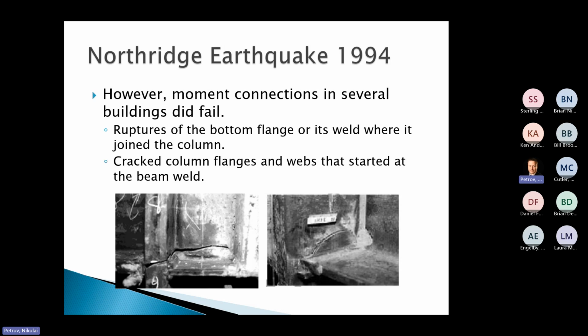But basically what was determined is that this system might have the strength that we designed it for, but it does not have the ductility that it needs to respond to an actual earthquake. And honestly, it kind of took moment frames off the table for a while.